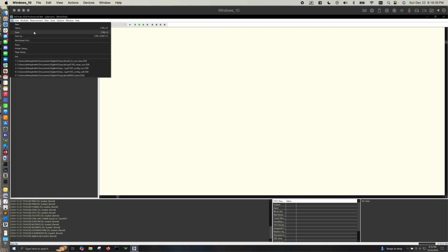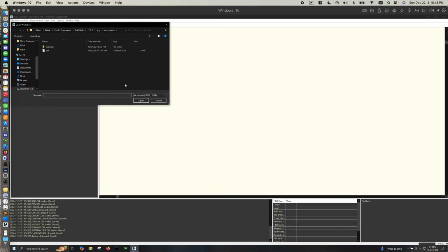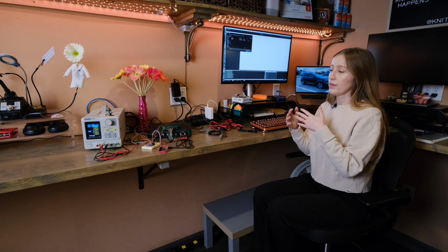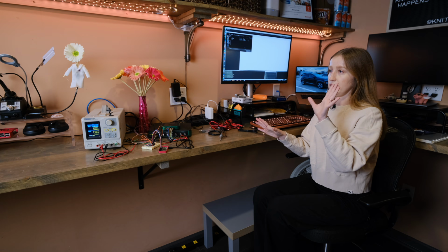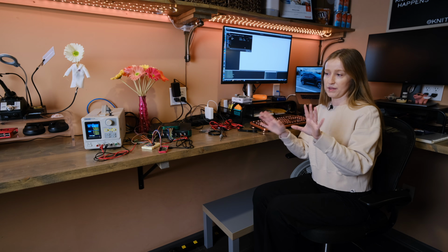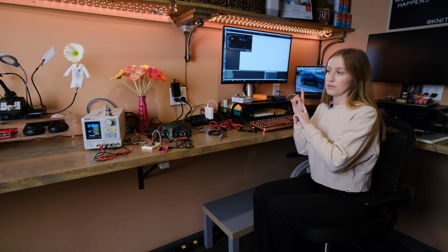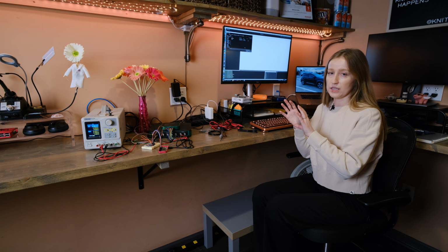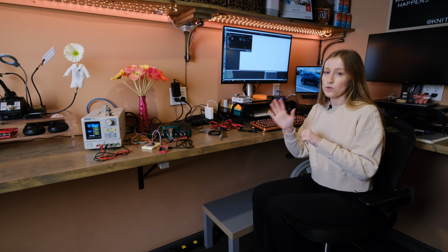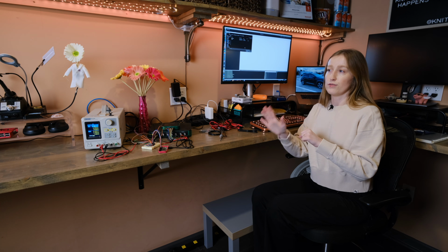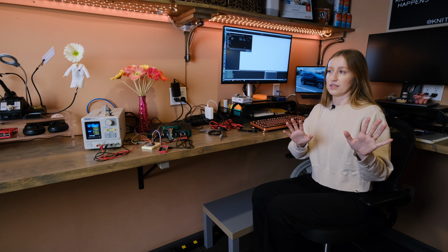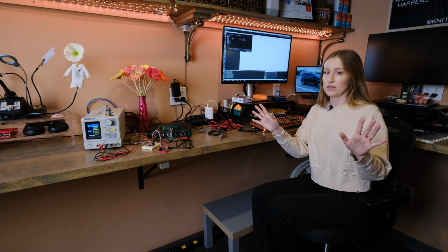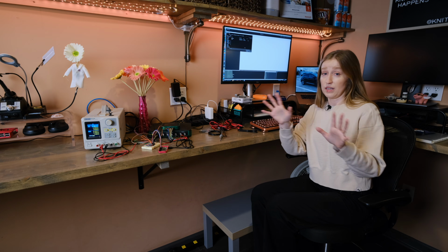One thing that did throw me for a loop in DASYLab is that even though your sequencer functionality and worksheets are all built into the same software application, the same instance running, a sequencer file is a completely separate file. Just because you have a worksheet open doesn't mean it's in the sequence file at all.